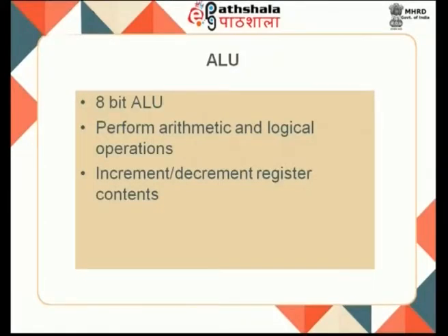It will send the data to one particular temporary register, and from there it will go towards where we want to have our results. When I am looking at a multiplication or division, by the time people will put the operands in the accumulator and B register. So, it has been confirmed that before doing this operation, your data should be moved towards A and B. Here A refers to the accumulator. So, the arithmetic operation is done and the results will be taken out, and this will be going towards your